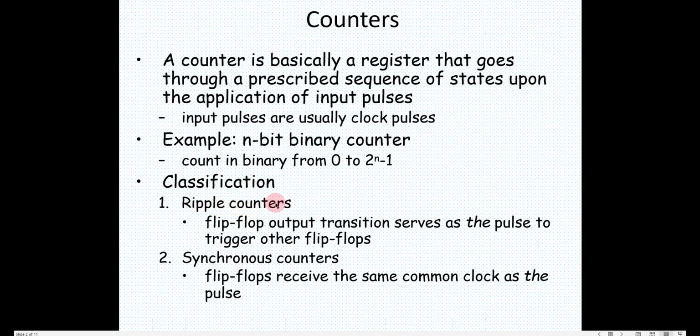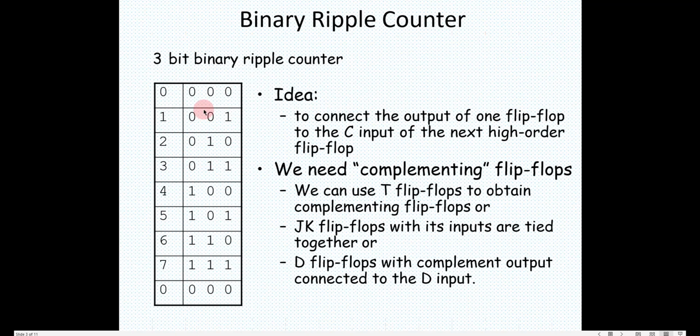So we will speak about ripple counters, and synchronous counters, which we did in the last class, used the same clock. So here now we are going to study about ripple counters. Ripple counters means the clock is not the same for all the flip-flops. It is an asynchronous counter. So let's see how this works.